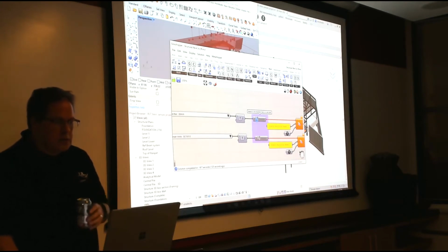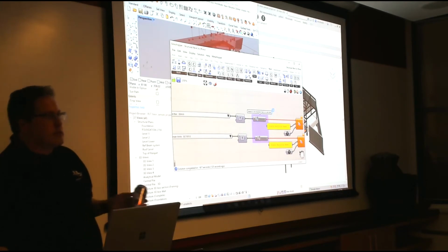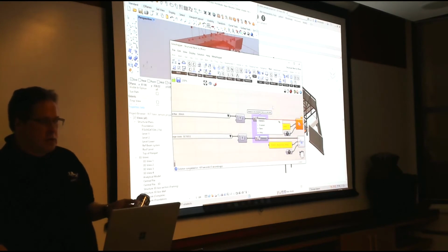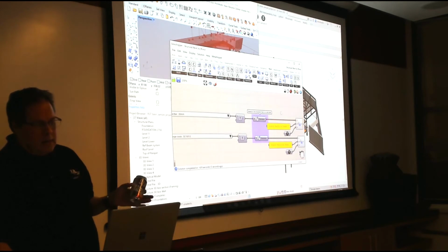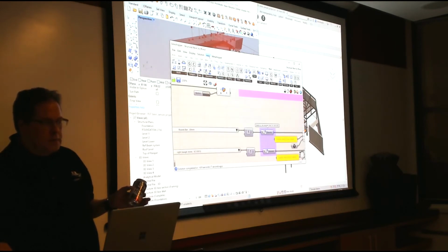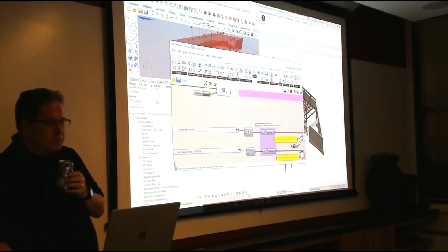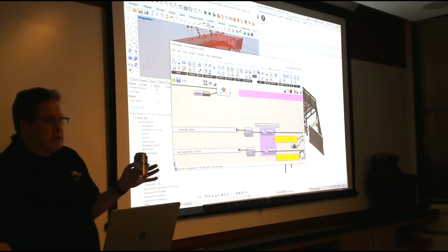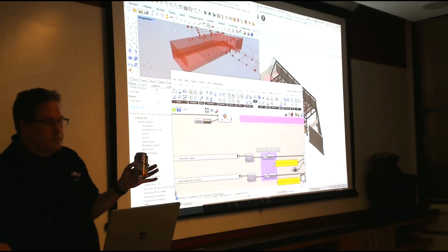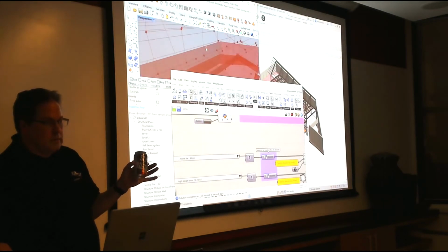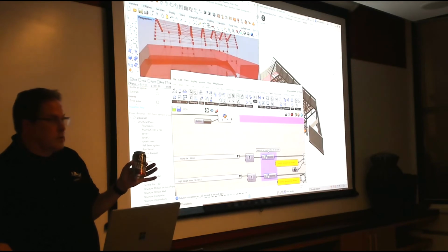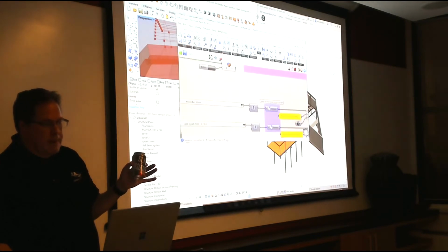And so what it's going to do when I enable those is it's going to go through and actually enable the analytical model on those objects. Okay, and let's try this. And then what happens is when I recalculate this thing, it'll hopefully give me the analytical model to those objects that the architect, I guess, didn't turn on the analytical model for. So there, now we have the stiffeners and everything else to that.